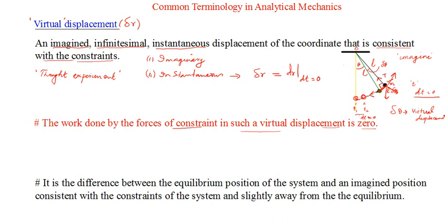And see, our permitted displacement, let me say that this is the linear displacement here. So let me use a color. Okay, I think you are able to see this one. This is the permitted linear virtual displacement, which I have represented by L delta theta. So it is the linear virtual displacement, and delta theta is the corresponding angular virtual displacement. Now you can see that the angle between the tension force, which is a constraint force, and the virtual displacement here is 90 degrees, right? The radius and the tangent are always perpendicular. That's the property of a circle.